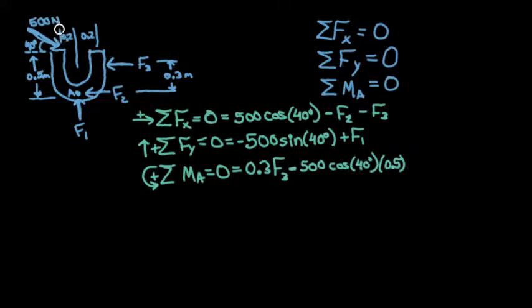And then the y component is also going to have a moment. Y component was 500 sine of 40 degrees, and that was pushing down. We go down, down, down, and we loop around A. And we see what direction we're going. We're going counterclockwise, so that's going to provide a positive moment. Perpendicular distance here would be 0.2 meters. Plus 500 sine 40 times 0.2.